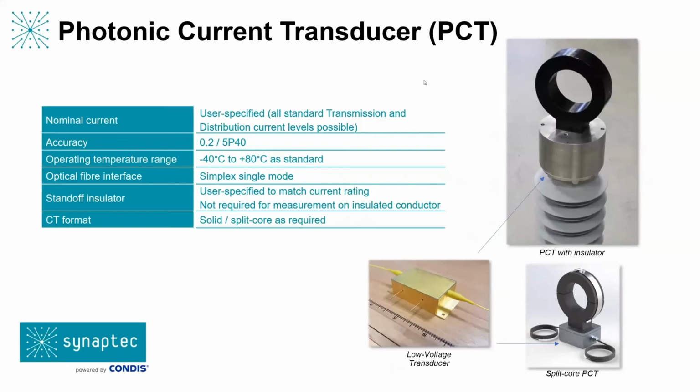And I think Neil covered part of one of the other questions, which is, how many bays can you instrument? The answer was already given, but just to be clear, per fibre, if we can do 50 locations and it's a 3-phase current measurement per bay, then you could do 16 bays per fibre. Then the question is how many fibres are available and how many bays you want to cover. It's completely scalable. There's no specific limitation on how many locations can be synchronously monitored, whether that's current, voltage, or other mechanical parameters. I hope that's clear.